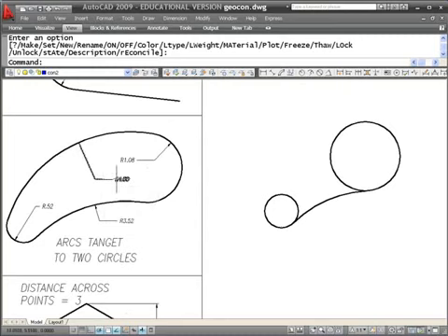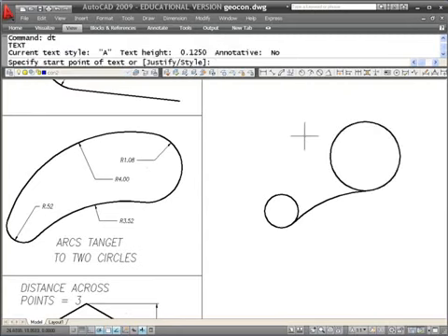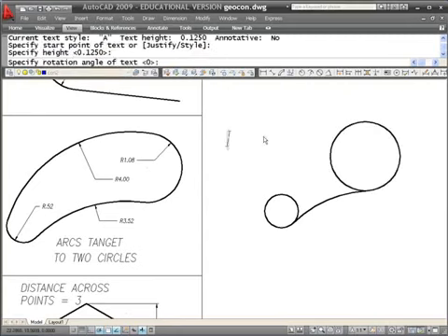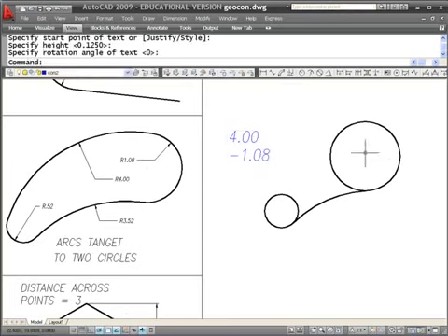What we're going to do instead is start at the same center, but we need to find a distance that is 4 units from the top of each circle, not from the bottom. In other words, from up here. Because the top of the circle is the distance from the center to the outside, or the radius of each circle away from the actual center, what we need to do is a little bit of math. And the math we need to do involves doing this. We need to start with the size of the arc we're using to connect the two. And then what we have to do is subtract, in each case, the radius of the circle we're concerned about.